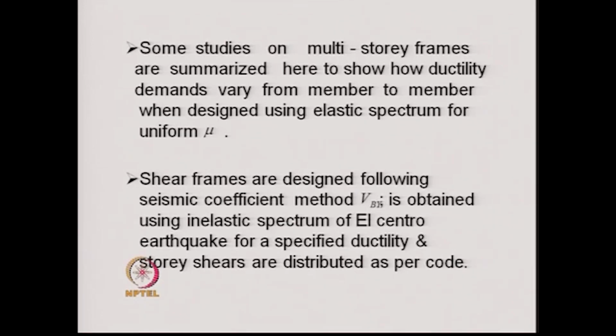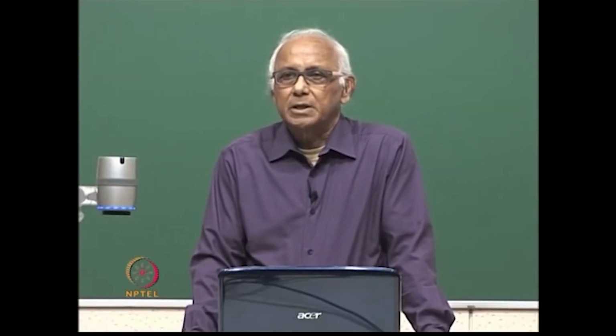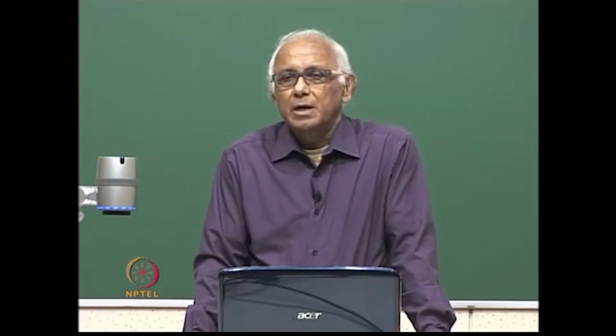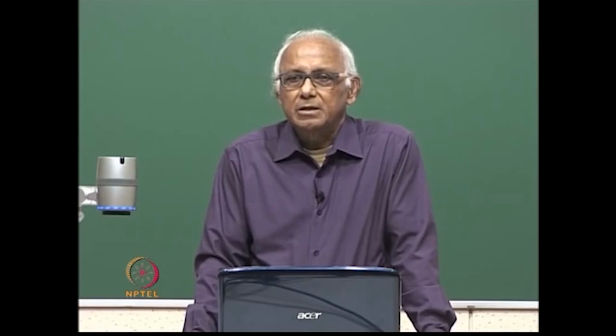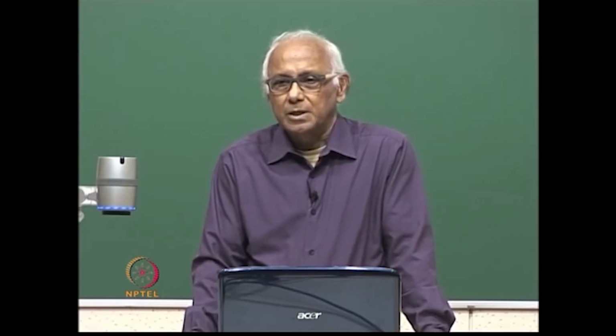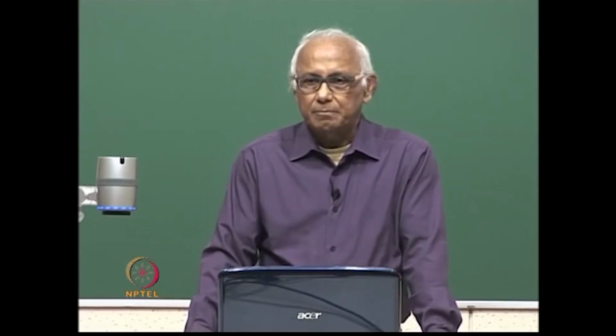Once the yield base shear for each frame is calculated, the base shears are distributed to the story shears, and this distribution is made as per the code provisions. This gave us the yield shear for each of the stories of the frame.